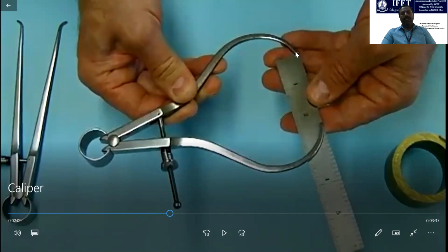They never know what is the value of the diameter, but how, because there is no graduation in this instrument, in this caliper. So the only way is they have to match it with a graduated instrument. Here they are using a steel rule, and by comparing, measuring the gap using the steel rule, they come to know the exact diameter of this hollow section.